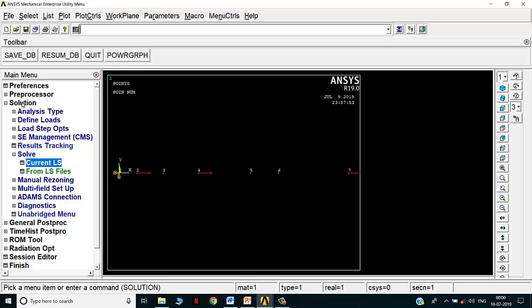So finite element analysis, where if you do the same problem with 300 elements manually, you are going to solve a 300 cross 300 matrix. So it is 301 cross 301 matrix. Reason being that if you have 300 elements, you will have 301 nodes. So one node greater than the element. So you are going to solve a 301 cross 301 matrix. Imagine how hard it would be doing by hand, but ANSYS solves it within seconds.